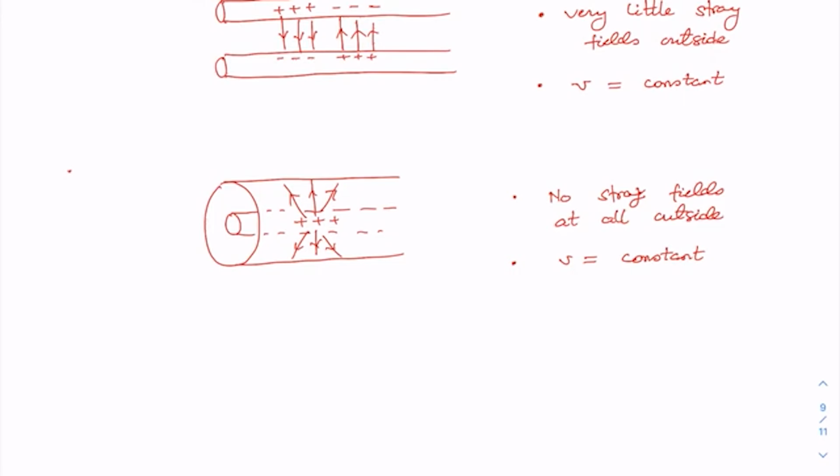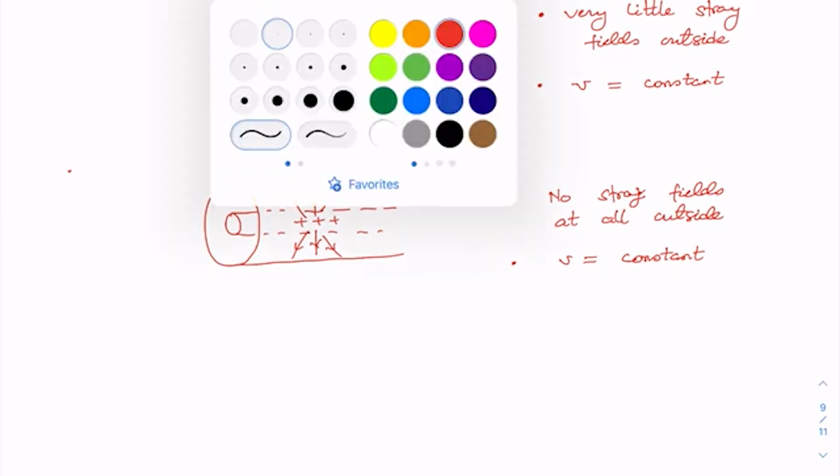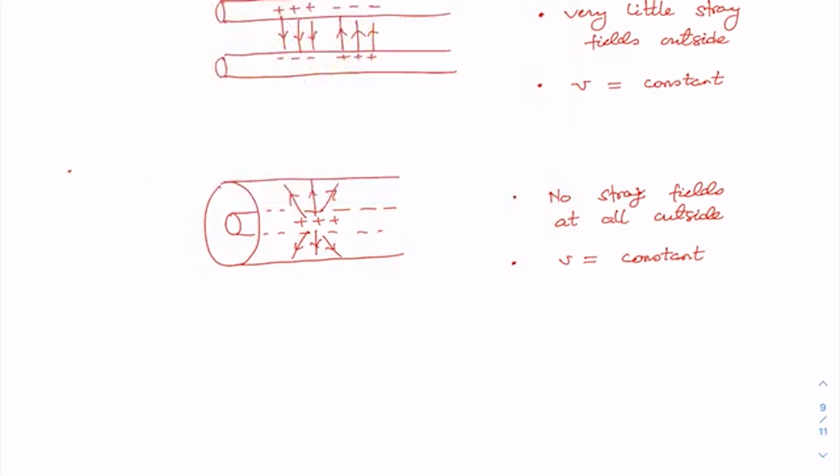In fact, this three-dimensional version of the coaxial cable transmission line could be realized as a two-dimensional version of a transmission line on a chip surface. Imagine a plane perpendicular to this wire, cutting the coaxial cable like this. It is going to cut these coaxial cables here, here, here.